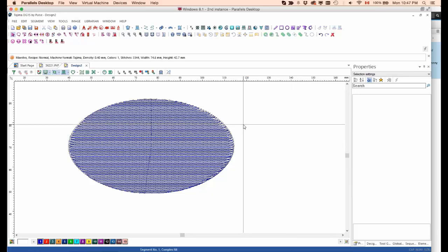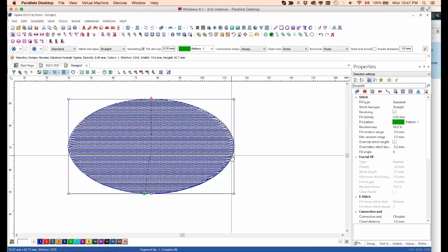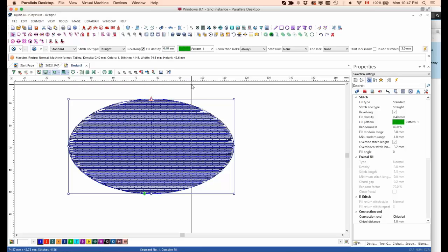Trevor, did that address the question? Yep. Okay, I got another one. Can you tighten the stitches, make the spacing closer instead of changing the shape at the ends of the stitch? Yeah, making it tighter in terms of changing the density, right? Usually the density that covers the fabric pretty well is 0.40. That's a density that will cover the fabric for sure.